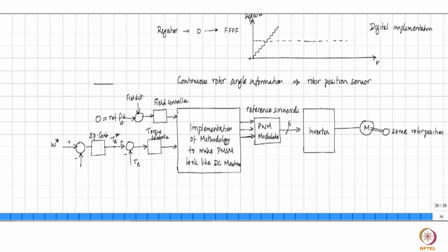The rotor is doing that job, right. You don't want to either increase the magnetic field of the rotor or decrease it under normal operation. So, you say that I don't want the stator to generate any magnetic field that is going to oppose the main magnetic field generated in the rotor. So, you keep that 0, whereas you focus on the other parts alone, right.